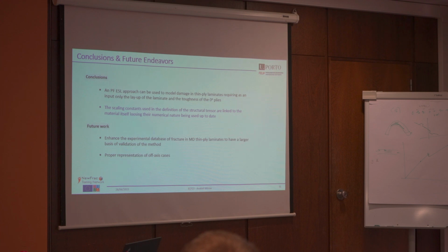and future work is what I'm going to try to do: make sure that in between the 2 anchor points that I mentioned, I'm representing the toughness of the laminate correctly, so I can extend the method to multi-axial loading or off-axis cases, in cases where you would have shear or anything else where you would not know how to predict the crack path, because here the expected crack path was actually following the x-axis of the tension. That's it.